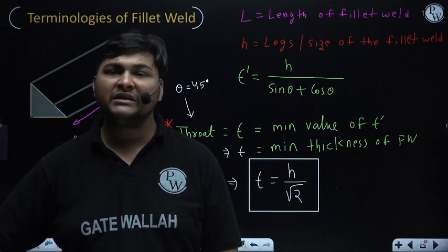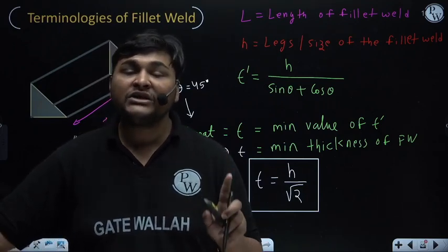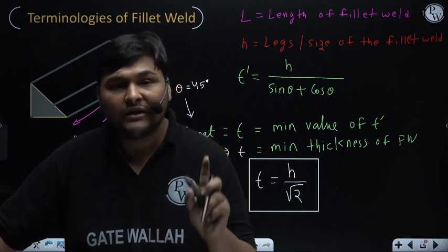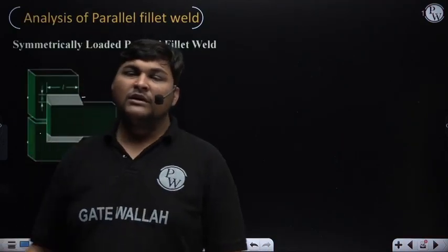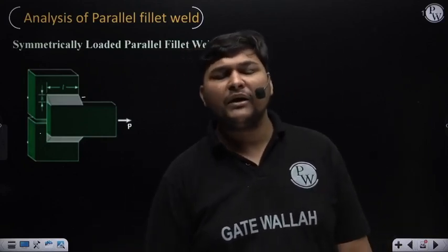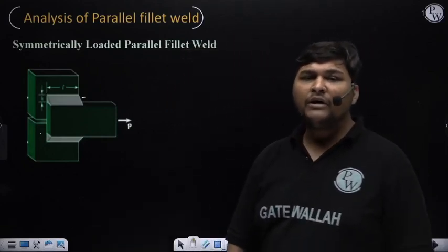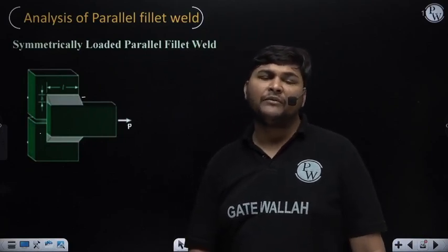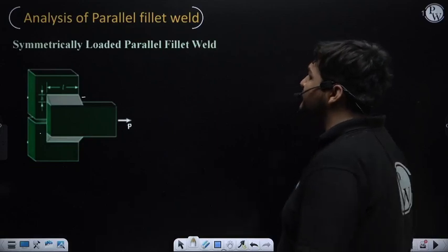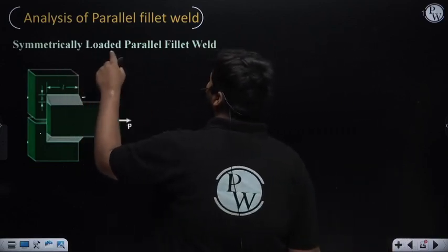After understanding this, we will start the discussion of the analysis of parallel fillet weld. Students, now we will discuss the analysis of parallel fillet weld. What is parallel fillet weld? I have already explained that. Whenever the weld length is parallel to force P, that fillet weld is known as parallel fillet weld. And in parallel fillet weld, the first case we will discuss is the symmetrically loaded parallel fillet weld.